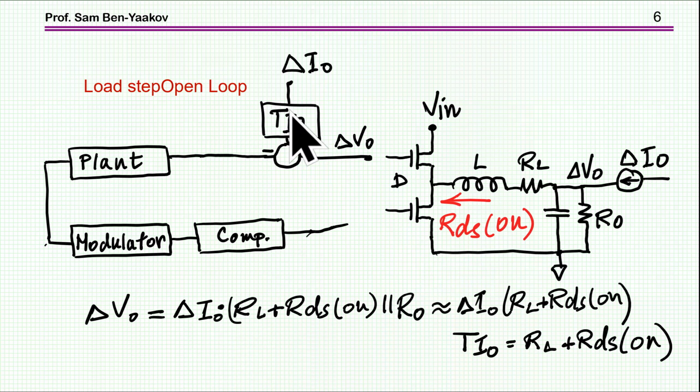Well, we can find it out by opening the loop here. We can do it since we have just schematics here, there's no problem opening the loop. We'll open the loop and see what is the transfer function in open loop between delta I and delta V. Now, we have a delta I, now it's coming into here, in fact, and what it sees at a given operating point without feedback is this, if this is a buck converter, a buck running at a certain duty cycle, at a certain operating point, a certain V in, and as we look into here, we see a resistance.